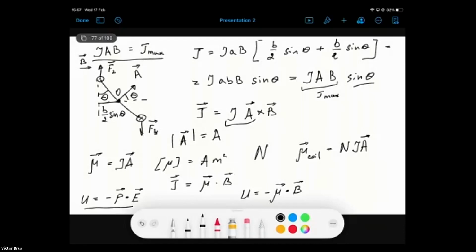So once we have some electric current when we measure, this electric current flows through this coil around the permanent magnet, and obviously there is some magnetic force acting on the parts of this loop, resulting in some torque. And this torque will be proportional to the magnitude of electric current. So we see here that this torque is proportional to electric current.